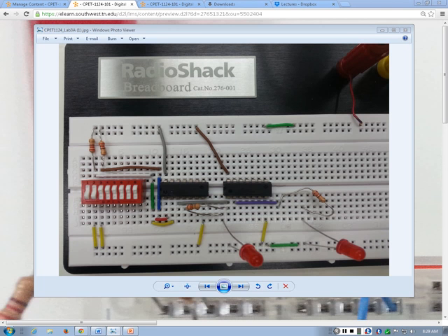Okay, and the resistor has to be here, and then look at this, how we are running the wires. I tried to take a neat picture. We ran 3 wires to connect the switch to the pins, but we could have run only 1 wire. I just wanted to make it a little bit neat. You will have needle nose pliers and a cutter stripper, so use those to push the wire and also cut it to make it small. There will be a bunch of wires, so try to reduce the waste. If you have small wires, you can keep them for the next circuit, so you can build the next ones.